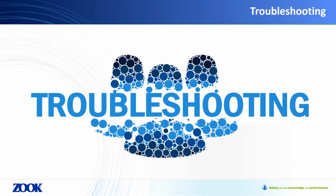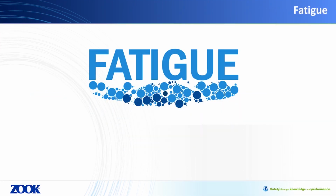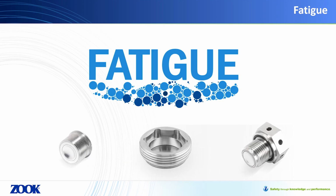It's important to remember that a rupture disc is a safety device that is designed to burst. Some people say designed to fail, but we like to say designed to burst or activate at an exact point. But like any engineered mechanical device, things can happen to affect performance, and this is when disc manufacturers have to use some detective work. First and foremost, rupture discs will not last forever. They are tension or compression loaded devices exposed to various forces, temperatures, etc. And therefore they will fatigue, sometimes bursting low is simply a case of service life.